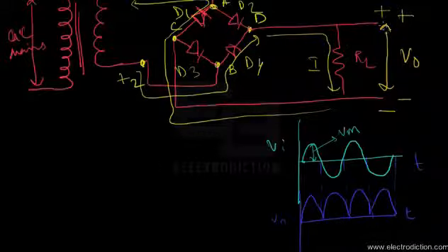So now since the output voltage across the bridge rectifier circuit varies in direct proportion to the input half cycles of the AC input voltage, they just resemble the input half cycles of the AC voltage, but contrary to that, there is no change of polarity as I showed here. Okay, so all the half cycles are of the same polarity in case of the output across a bridge rectifier. So this output, as you can see here, keeps on varying with time, sometimes increasing and decreasing. So this is termed a pulsating DC output.